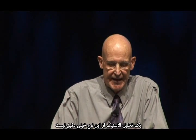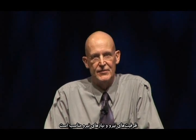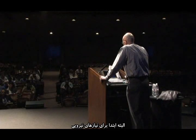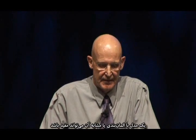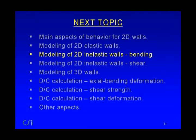And that really is a key point. If you're using true strength-based design, an elastic analysis of this type is nowhere near accurate, but it's plenty good enough for getting force demands and force capacities, or force demands primarily. If you're doing an inelastic analysis, that is really no longer the case, and a mesh like this may actually be counterproductive. I'll be talking a little bit more about this. Let's look at the modeling of 2D inelastic walls now.